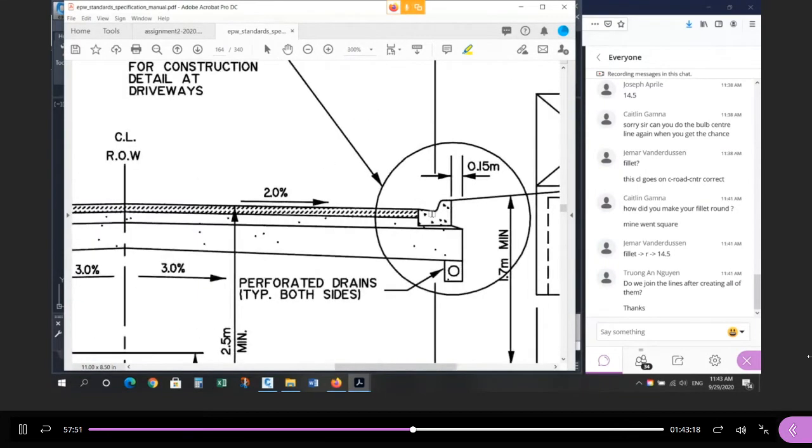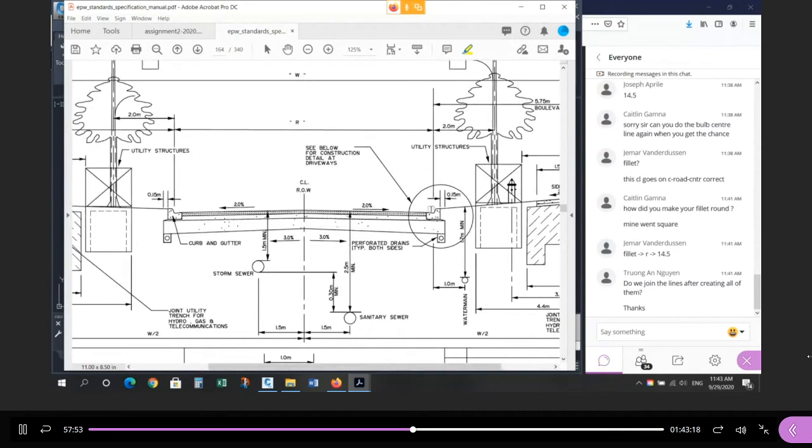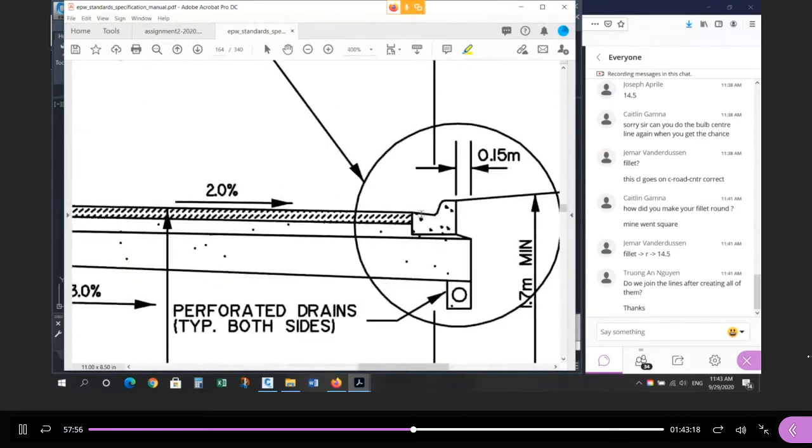And you can tell by this drawing, right? You can see the dimension line, this vertical line goes to the gutter, not the edge of asphalt. So we don't even draw this in the drawing. We draw the position of the gutter. So when I say to you, draw the edge of pavement, and we're dealing with Richmond Hill, I really mean, more specifically, draw the location of the gutter. Is everybody clear? Okay, and I'm not doing this just to cause you grief. It's the reality of the situation. The word pavement sometimes means the gutter, sometimes means the edge of asphalt.